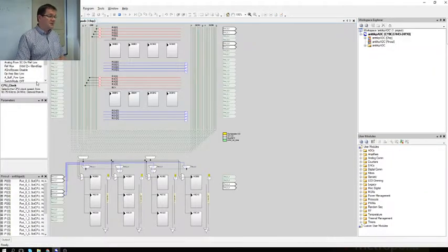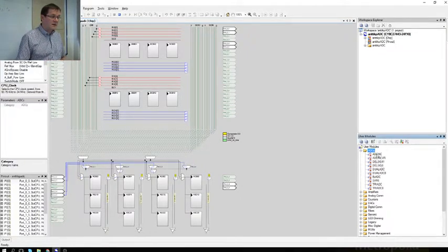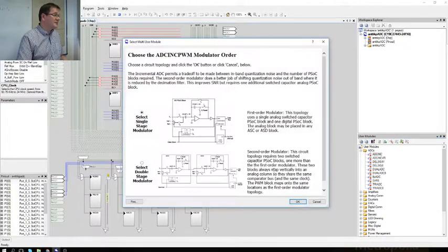There we have the chip design first, and we just take the A to D converters. For selecting the A to D converter, you can refer to the Cypress Semiconductor application notes. I'll just take the first one, ADC incremental A to D converter, and for clarity, the first one with the first order modulator.